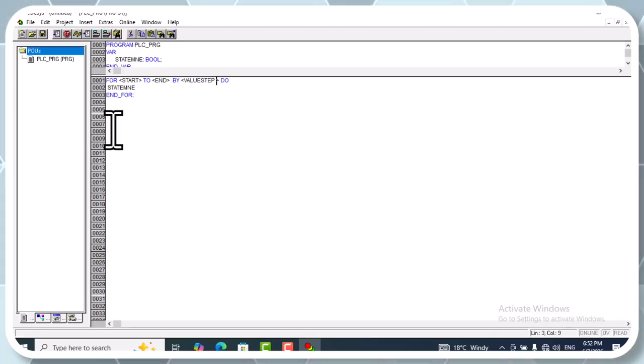So when you use a small PLC type, especially you must check the memory capacity and the scan time of the PLC. It's recommended to reduce the FOR DO statements or split up the FOR DO statement into smaller ones.